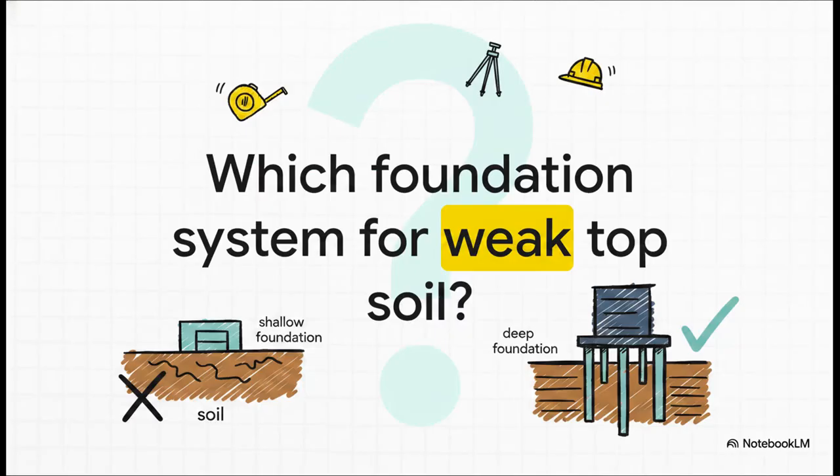Okay, let's test your understanding right now with a quick pop quiz based on our geotechnical chat. Which specific type of foundation system is required when the topsoil is just too weak to support a structure? Think about it for a second. Well, if you answered deep foundations such as pile or pier foundations, you are absolutely correct. Shallow foundations simply won't cut it if the surface bearing capacity is insufficient.